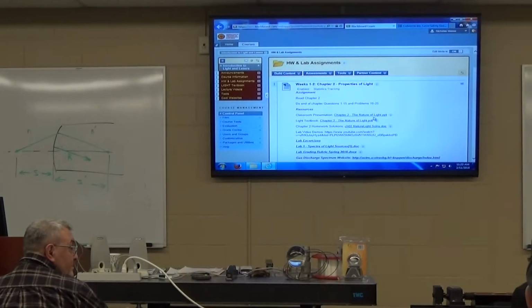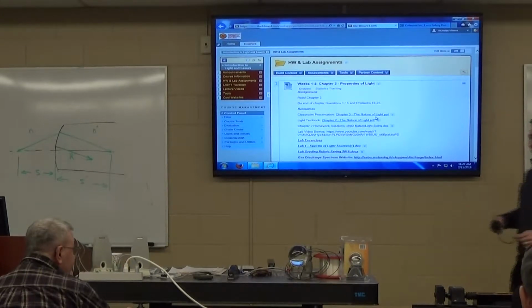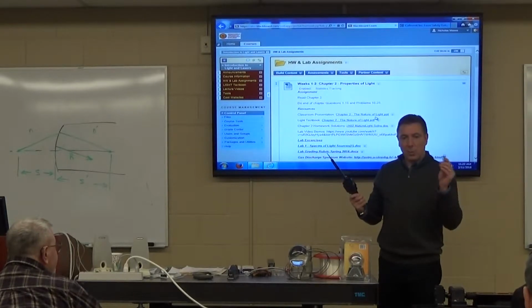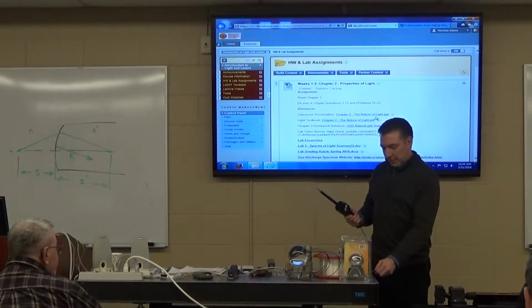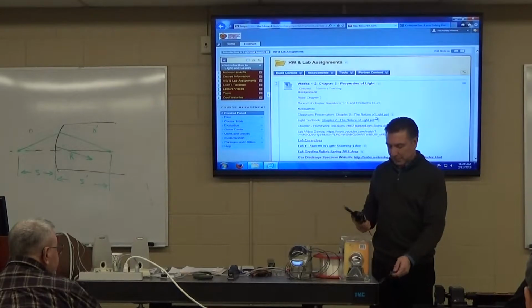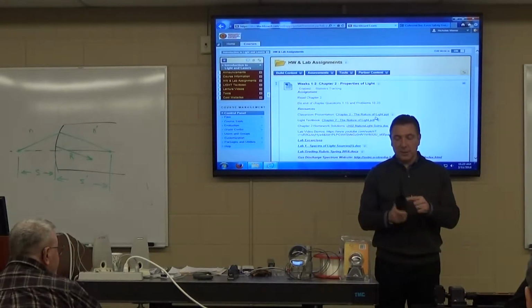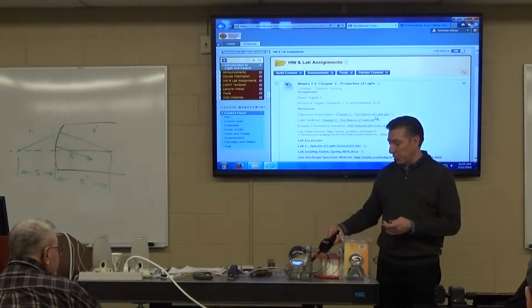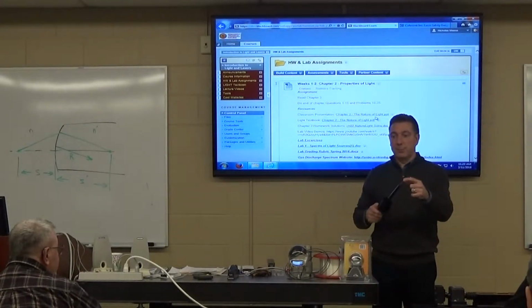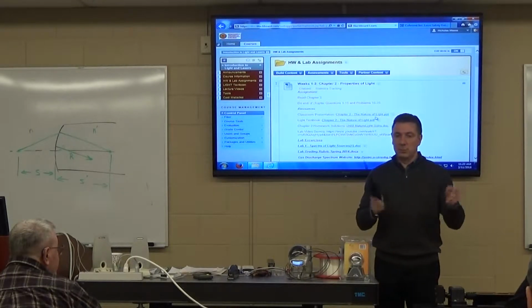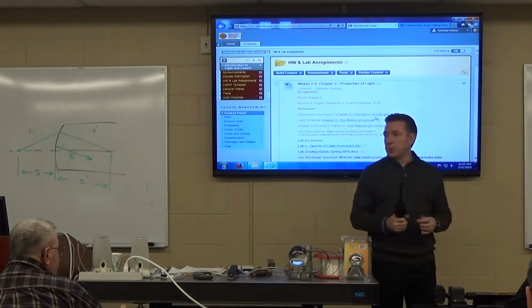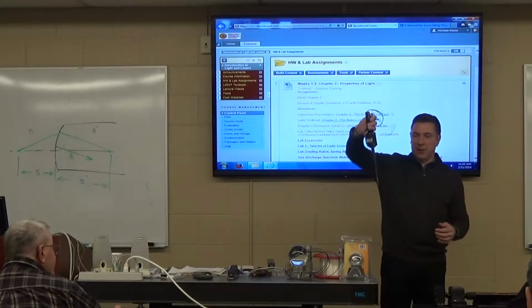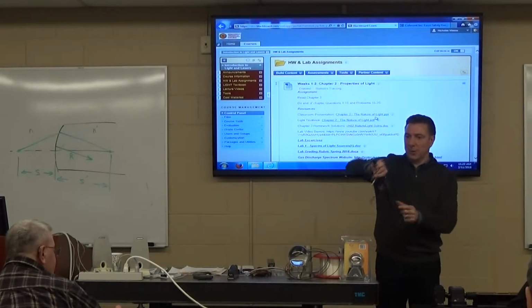So before you work on anything that has capacitors, whether it's a laser or any other piece of high voltage equipment, you ground one side of this to the third terminal on your outlet, and then it's got a kilovolt meter on this, and you go through and you touch all the leads on the capacitors to make sure that whatever charge is built up in there gets dissipated through the discharge stick. Usually, industrial lasers have cabinets with the power supply in it. These are usually hanging right inside the door on those.